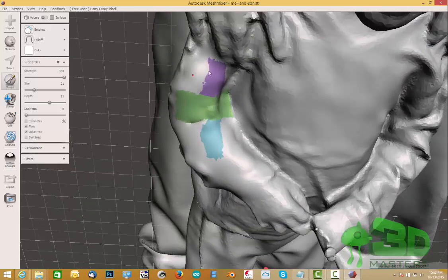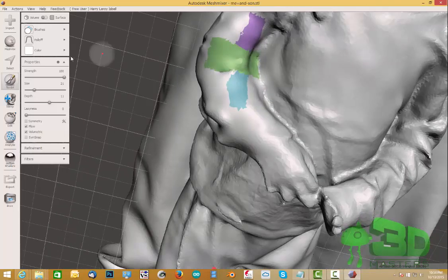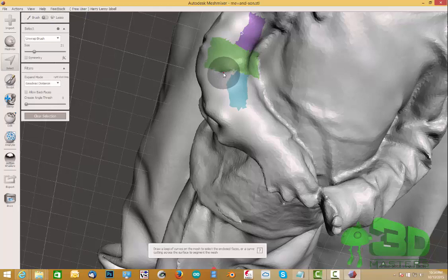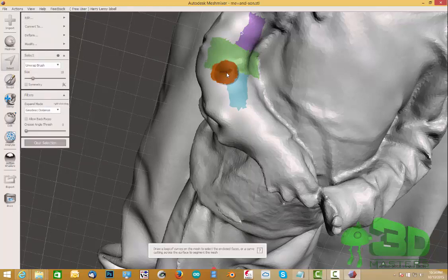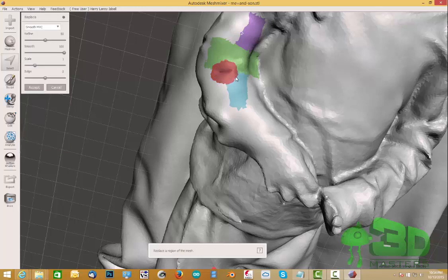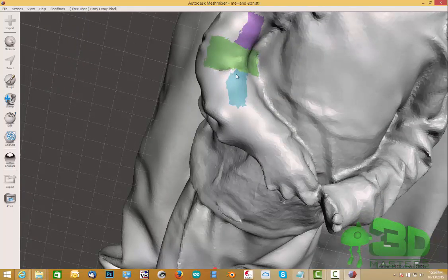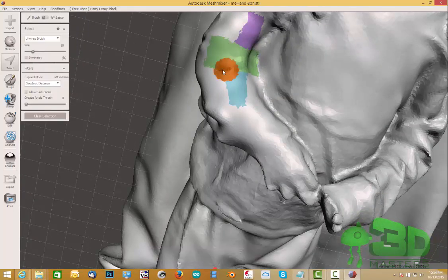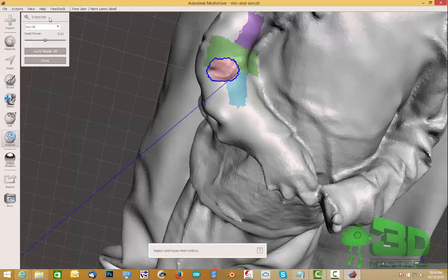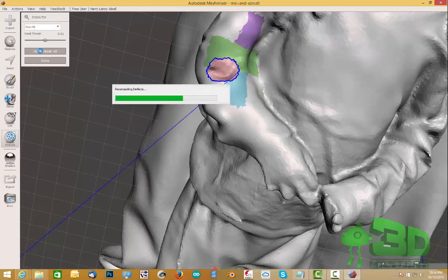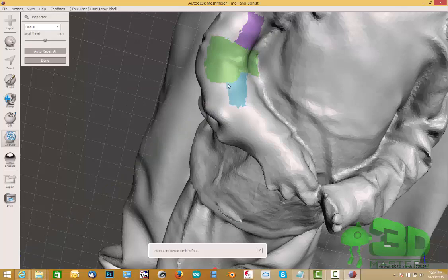Yeah, definitely liking this. And it looks like it's folded in on itself right here. So remember, you learn the technique on how to select an area, and then you can hit F, and it'll... nah, it didn't do it. Because it's folded in on itself, because there's something else behind it. So let's do select again. I'm just going to select this area, hit X and remove it. And then I'm going to go to the Analysis and the Inspector, and then repair that hole.